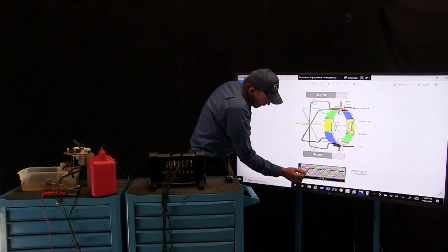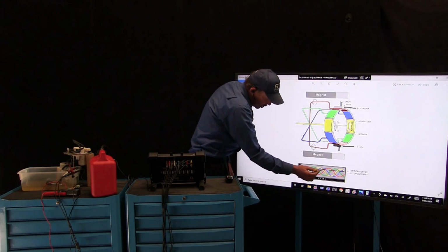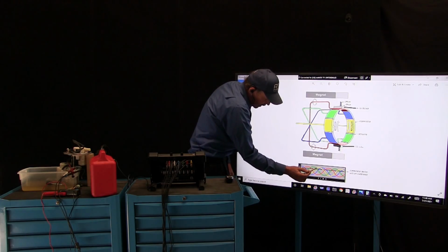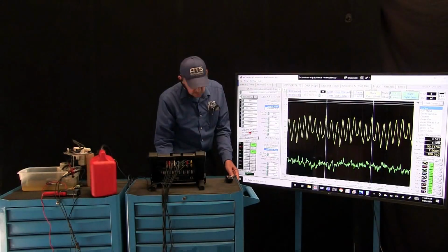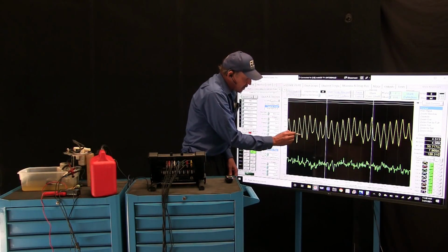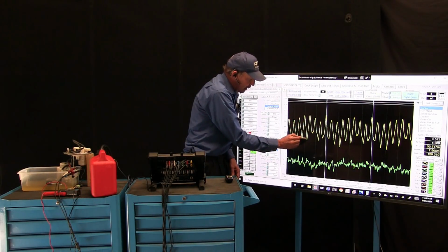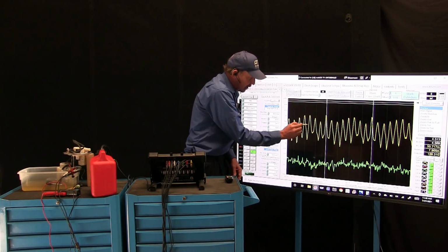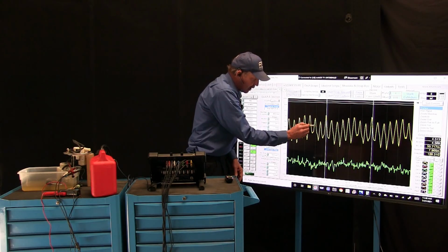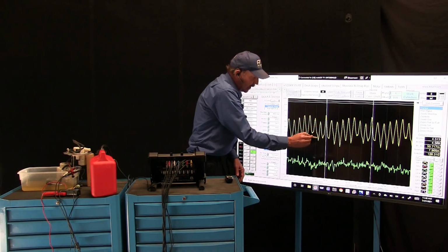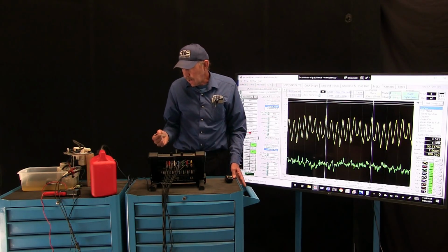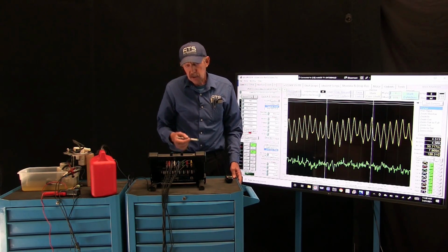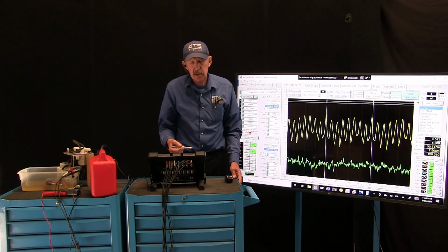So each one of these is the pull from each commutation bar. What you're seeing right here is what we're really seeing back over here. Each one of these is the current going through the winding. This is where we went across the insulation, current pull, the next current. So we can check each winding, therefore I can check the speed. As we can see right now, when you lose pressure, the speed of the pump has to increase.